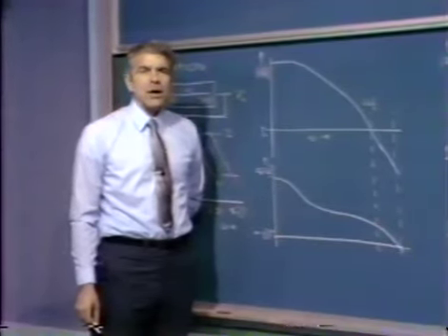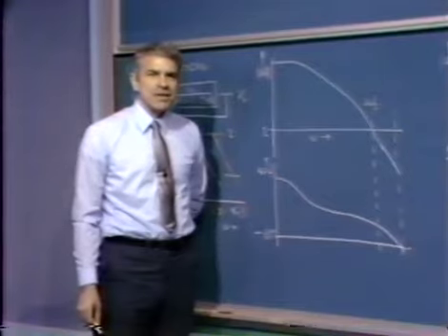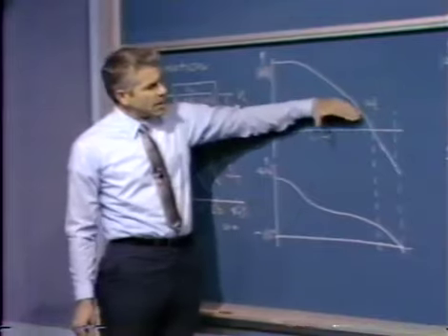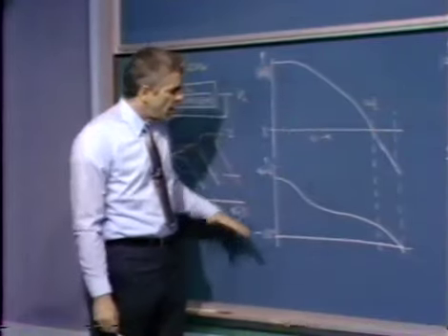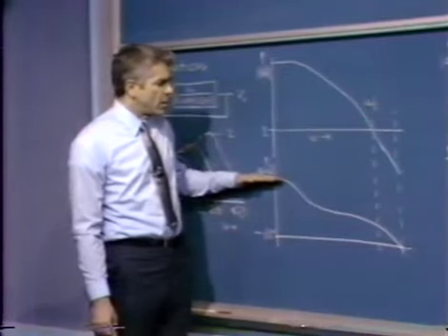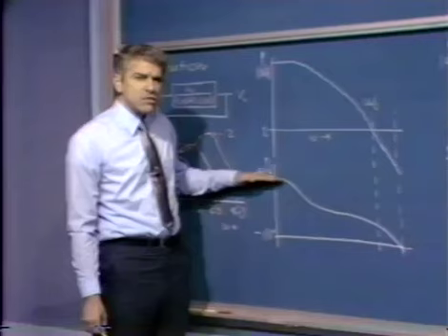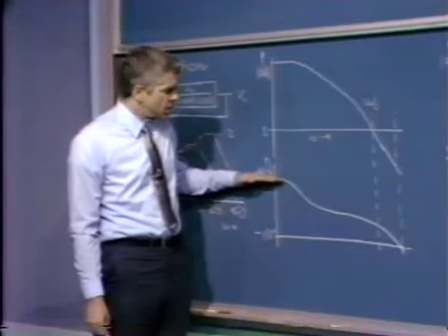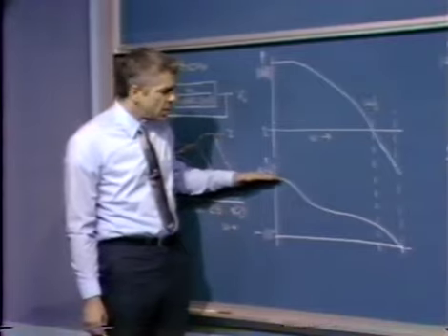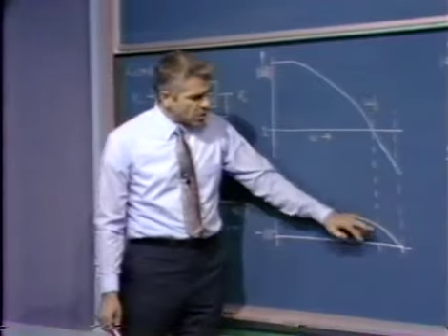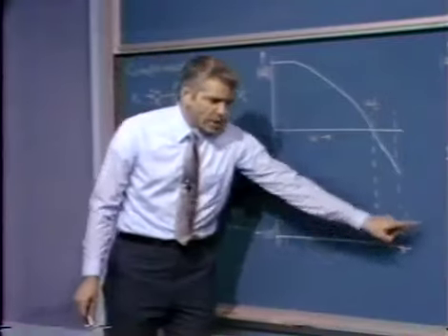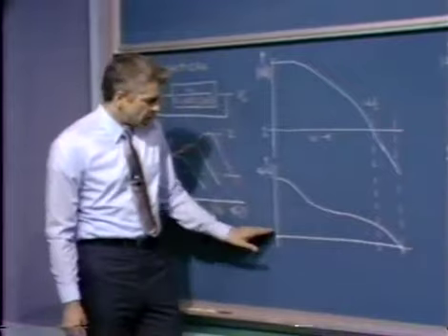And if we have sort of a well-behaved, maybe typical common kind of a system where the magnitude is sort of a monotonic decreasing function of frequency, the angle starts out possibly close to 0 degrees, or in the case where our loop transmission includes an integration, which is a fairly common case in mechanical systems, the angle of the AF product would start at minus 90 degrees, and then again drops off and goes through minus 180 degrees only once. It doesn't wiggle back and forth around the minus 180 degree line.